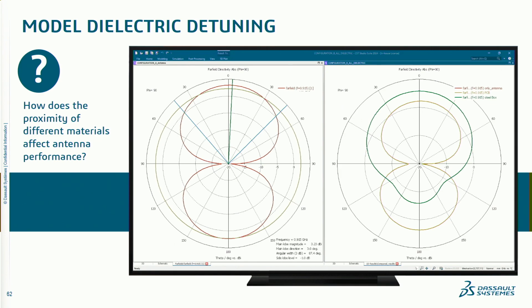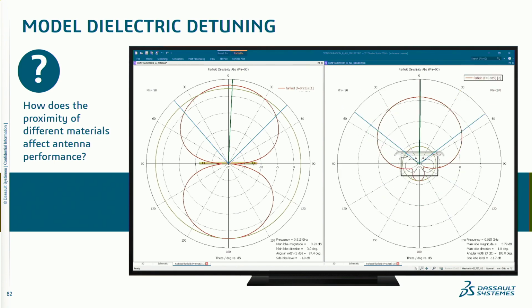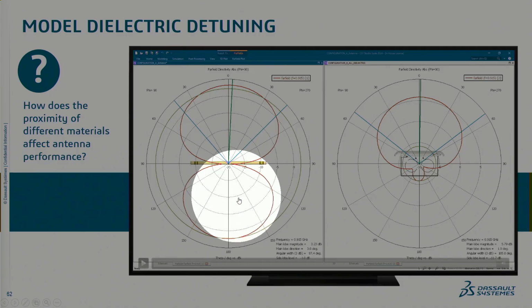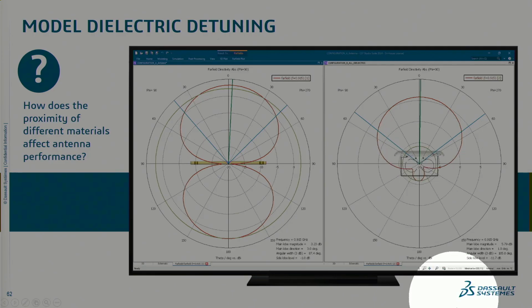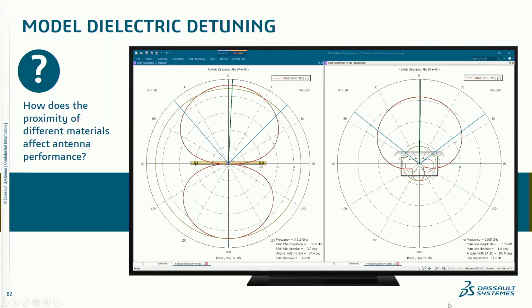It's not just the overall performance, it's the directivity. On the left, you see very uniform front and back performance. On the right, well, that box has completely killed any sort of antenna performance around the back of it. You can kind of see it silhouetted in there. We project very well forwards through the plastic cover, but not backwards. And that's something you have to keep in mind during design. You can't just place one of these in a center wall in the house and have it connect to things on various sides of it.